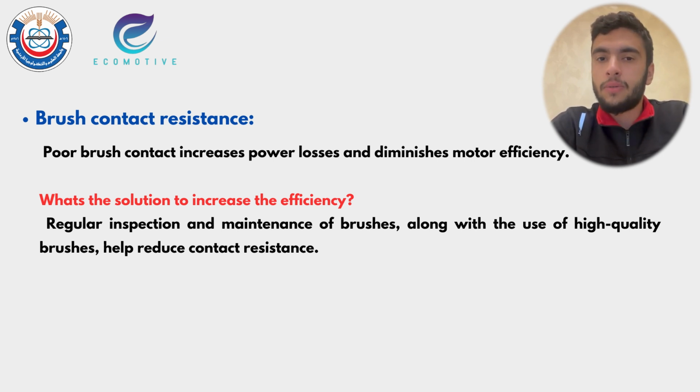So what is the solution for that? What is the solution that will help you? Well, first of all, regular inspection and good maintenance of the brushes, so you will take care of it. And also you need to use high quality brushes. If you did all of that, that would really help you to reduce the contact resistance.